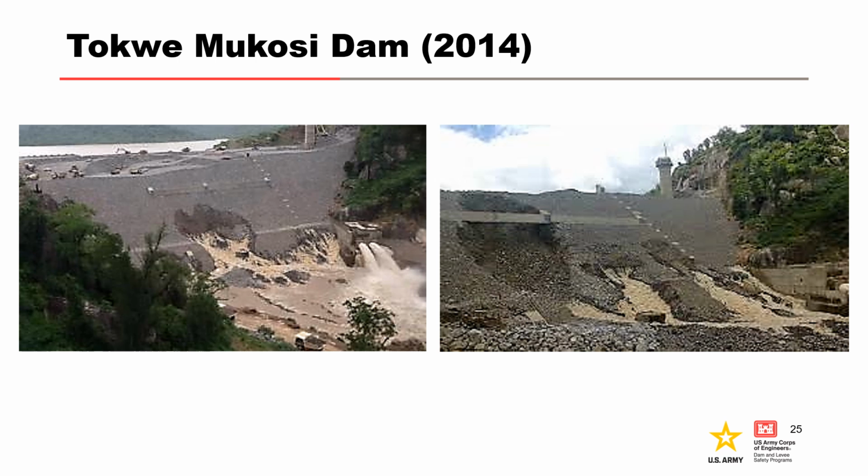Here's an example of a dam that survived large seepage flows. Construction on the 300-foot-high concrete-faced rockfill dam on the Tokwe River in Zimbabwe began in 1989. The upstream face was being prepared for the concrete facing to be placed last. Extreme flooding occurred when the rockfill embankment was 60% complete, a height of about 200 feet. The water level rose to within 5 feet of the existing crest.